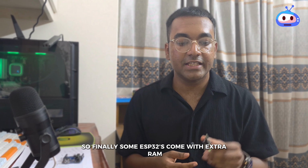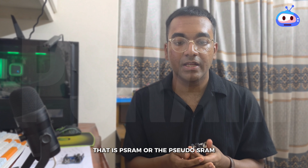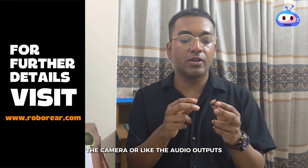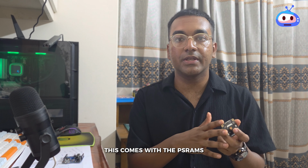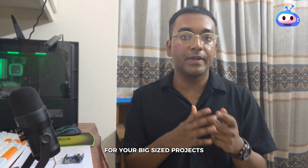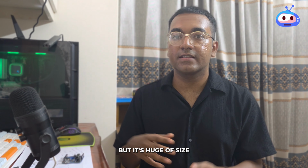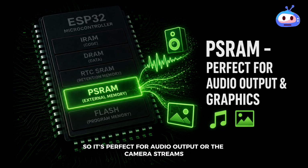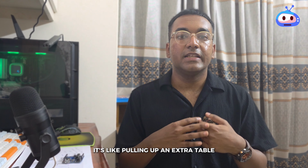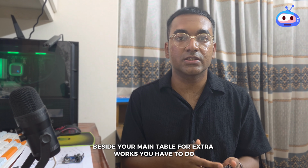Finally, some ESP32s come with extra RAM, that is PSRAM, or pseudo SRAM, like the boards that have a camera or audio outputs. This is extra memory that comes with the board for your big sized projects. It's slower than the internal RAM, but it's huge in size. So it's perfect for audio output, camera streams, or complex graphics for your projects. It's like pulling up an extra table beside your main table for the extra work you have to do.